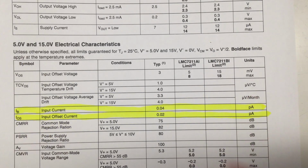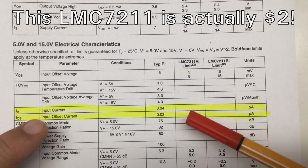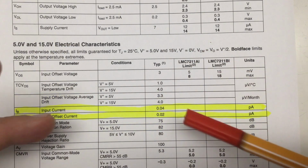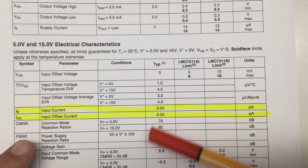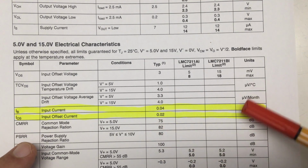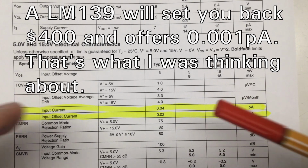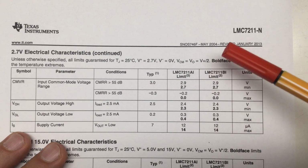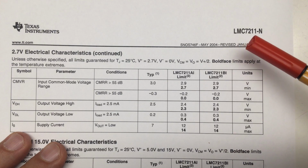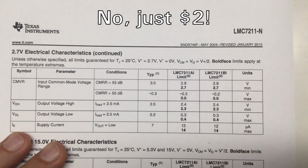And if you are willing to shell out a few $100, you can get analog comparators and build a Schmitt-trigger circuit around them, and those can offer you input currents, respectively input offset currents, of 0.04, respectively 0.02 picoamps. So even several orders of magnitude better than our CMOS 555. And this is the data sheet of the Texas Instruments LMC7211-N. As I said, you have to dash out a few $100.